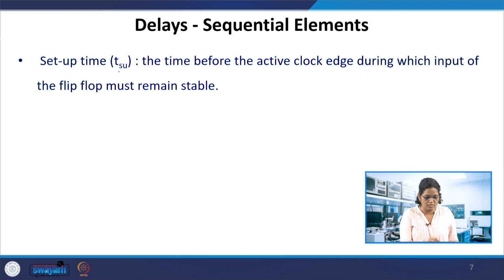And then one is the setup time, which was mentioned. Setup time is, in the case of flip flops, if we take the clock edge, the passage of the clock, and the data change at the D input of the flip flop, there should be a minimum time for which the data should not change before the clock edge becomes active. That is the setup time of the flip flop.